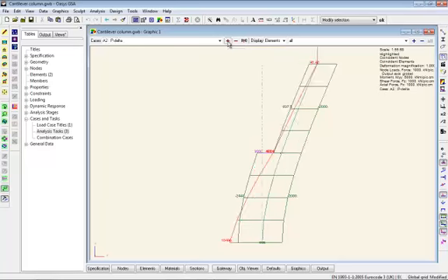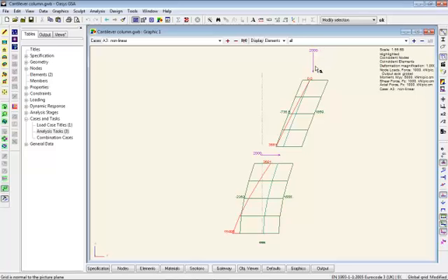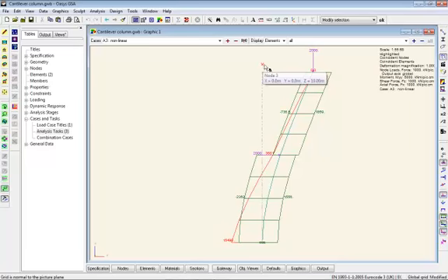So if we look at the P delta option, we'll note that the axial load remains constant down the column, but we are getting shear force and bending moments in the upper part of the column, and we're also getting more deflection on this structure. And similarly, if we go for the non-linear, we're getting moment and shear force to the upper reach, but we're actually getting less axial load, curiously enough. But we're also getting an overall rotation of the structure.